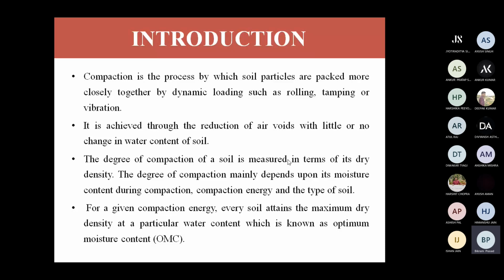If you have excavated some parts of the field, obviously some loose soil particles are there. So by removing those soil particles and tamping properly, we can make it compact.